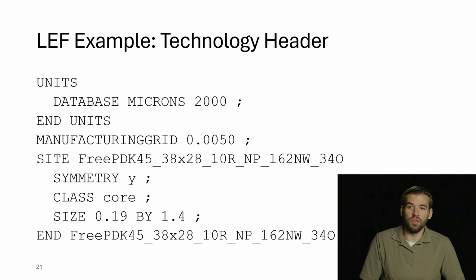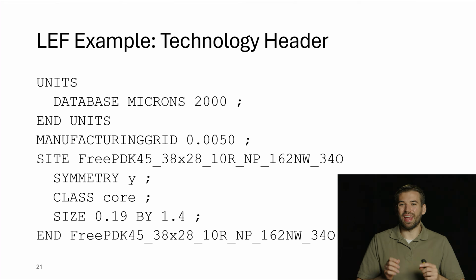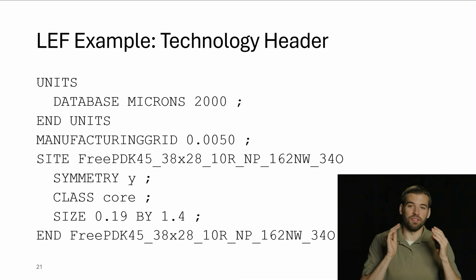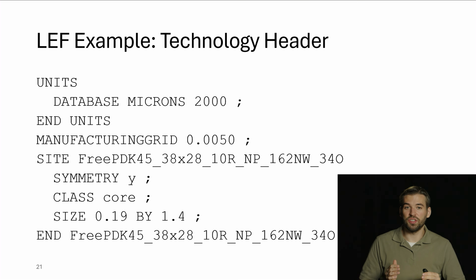In this example, the scale factor is 2000, which means that every DBU is going to be 1/2000th of a micron, or 0.5 nanometers. So this is essentially a way of reflecting that for this technology, there is nothing that requires more than a precision of 0.5 nanometers. This simplification is so important that EDA tools encoded it here in this LEF format to recognize this.